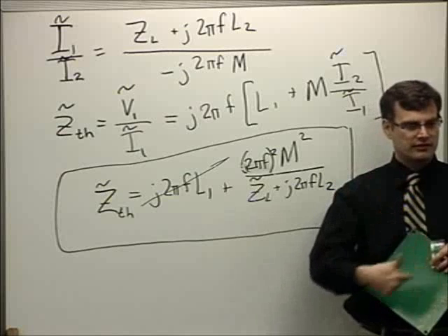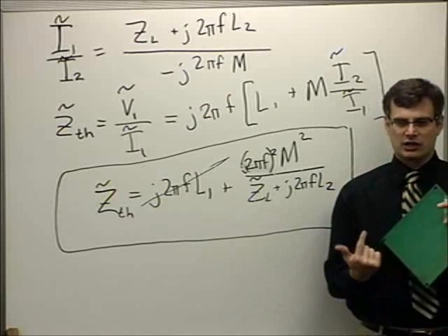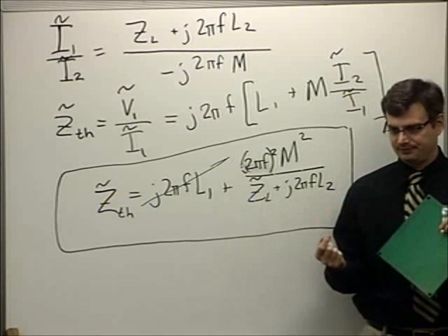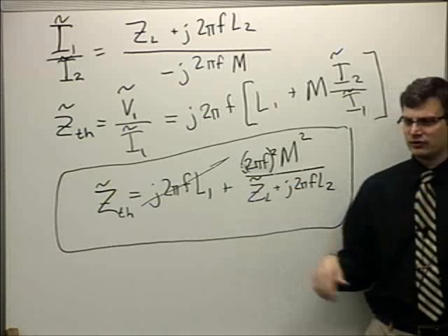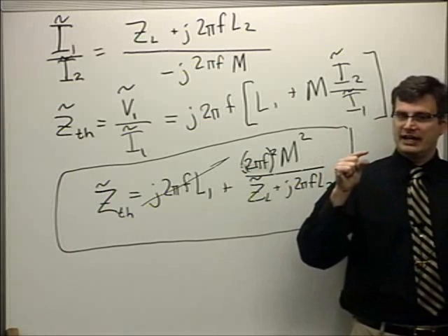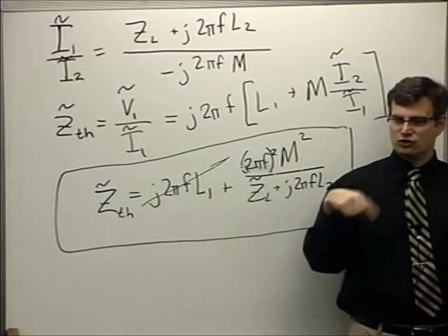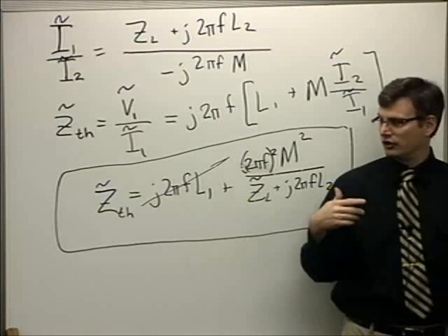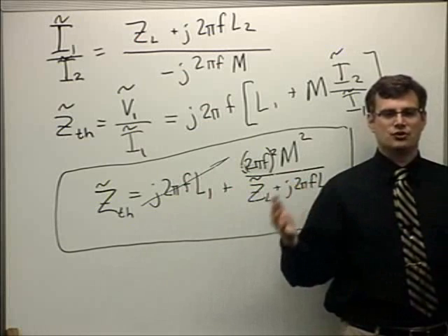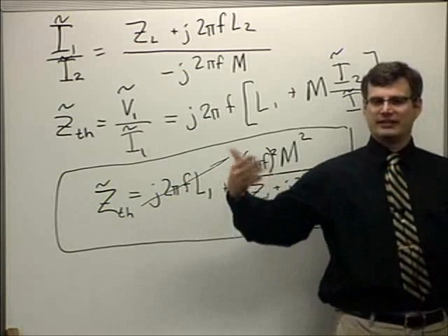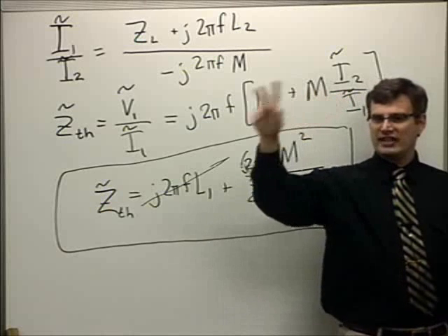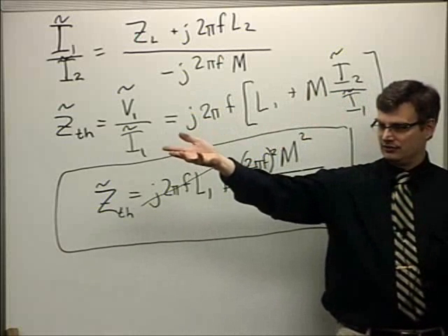Usually these are a coil of conductors, and the coil is kind of closed-circuited by a chip, an RF integrated circuit, RFIC. And that RFIC has several different types of electronics on it. The first thing it has is a charge pump, which basically rectifies and steps up the sinusoidal current. So in this system, you hit it with magnetic energy. The charge pump drinks up the magnetic energy, rectifies it, and pumps up a DC voltage level so that it can turn on the rest of its logic circuitry.